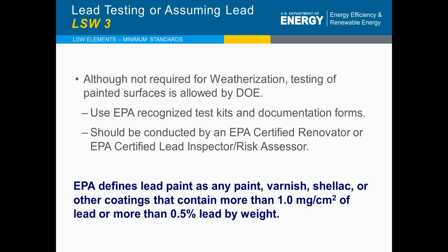Testing, same. We're not required in LSW to do testing, but if we do testing, we must follow EPA guidance here. The testing must be done either by a certified renovator, if it's of certain types, using EPA-recognized test kits or paint chip sampling, or if it is done through another means, it has to be done by a certified lead inspector or risk assessor.